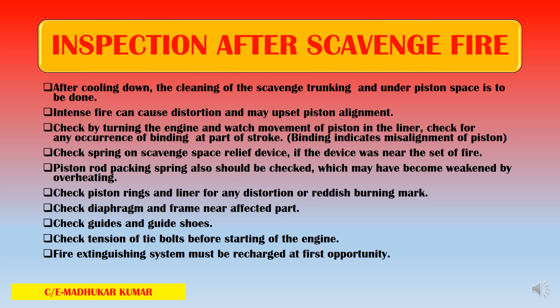Intense fire can cause distortion and may upset the piston alignment. That also has to be monitored and checked. Check by turning the engine and watch the movement of the piston in the liner. Check for any occurrence of binding at any part of the stroke. Binding indicates misalignment of the piston, so any binding should not be there.